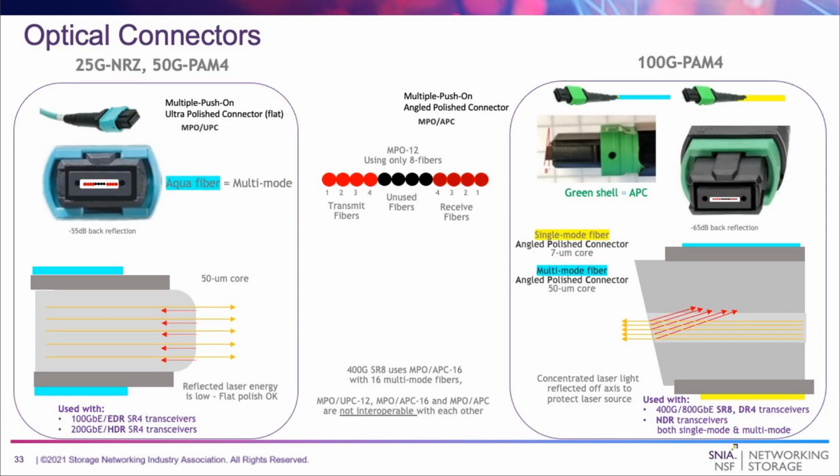So each of these has a place in the data center. In the past we've used the multiple push-on optical connector for the 8 fiber parallel. There's actually 12 fibers, but we use 4 transmit and 4 receive.